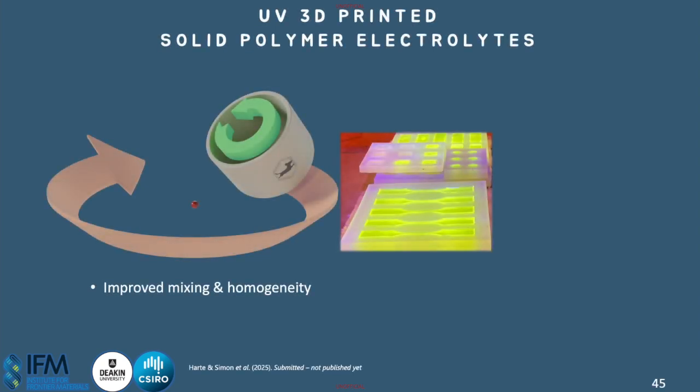To improve mixing and homogeneity, we mixed using a Thinky mixer, a centrifugal mixer, which, because we were using a resin system that didn't have catalytic curing from the solvate ionic liquid, let us mix these systems much more homogeneously, and also do degassing using the centrifugal mixer.